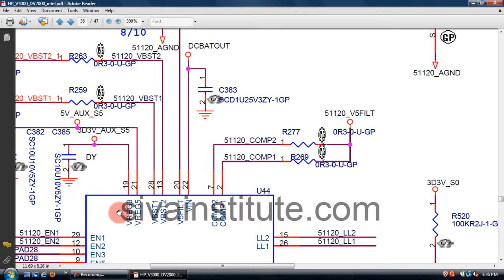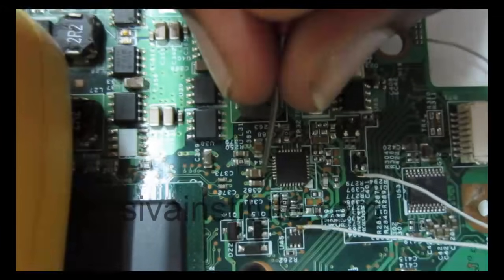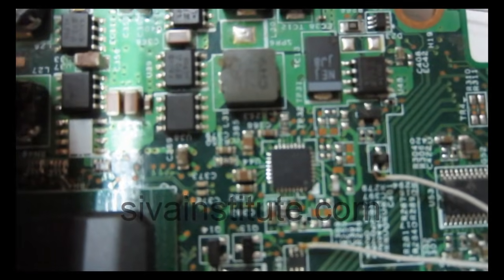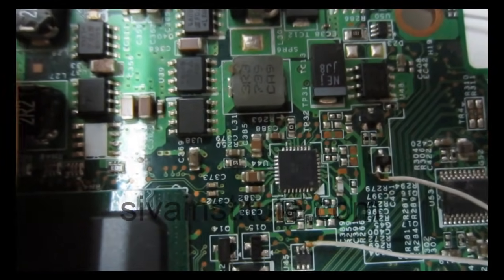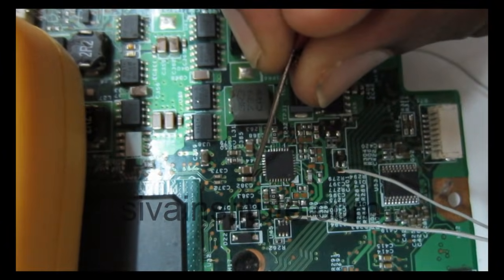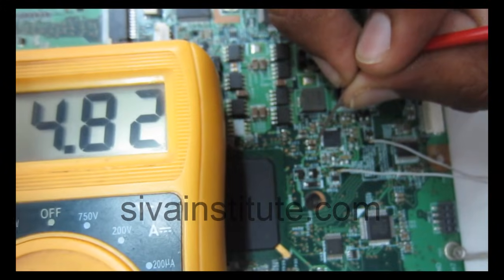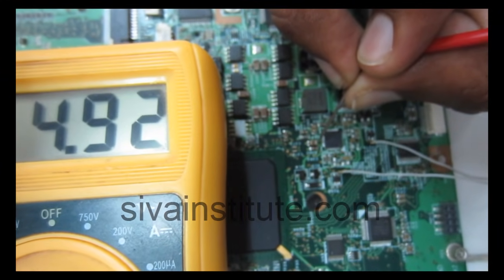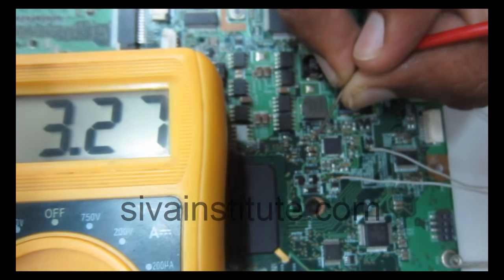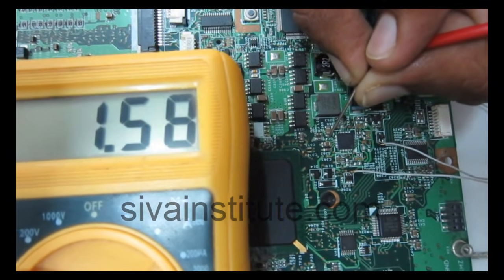This 3 volts goes to the SIO chip. We will see the U44 IC. We will check the voltage here. 4.9 volts. So 5 volts is OK. Next, 3.3 volts. See here, 3.27. That means 3.3 volts. So the first step is OK.